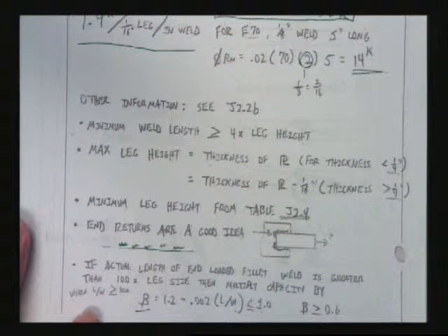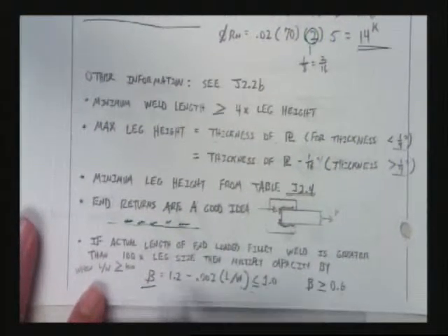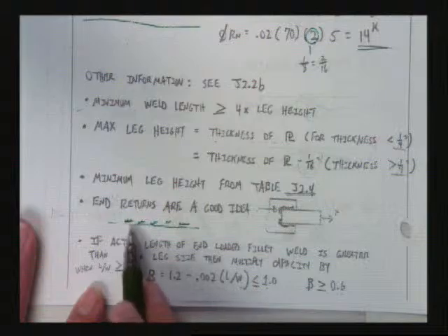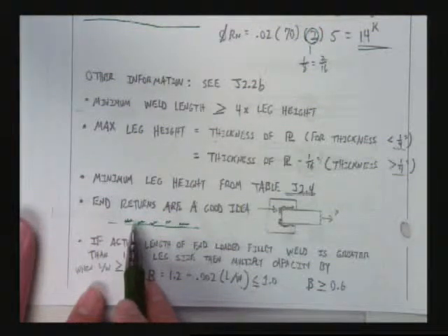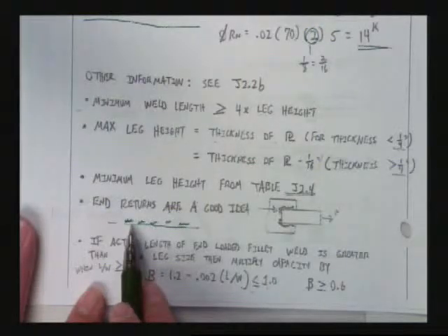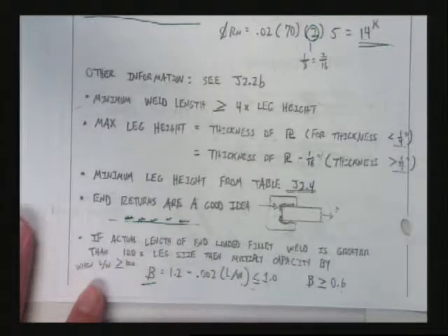Individual welds together, much easier, okay? There's problems with stitch welds. Every time you start and stop a weld, it's not the best material, okay? That provides more of an opportunity for fatigue failure, all right? But there's plusses and minuses, all right? And that's what people commonly use.